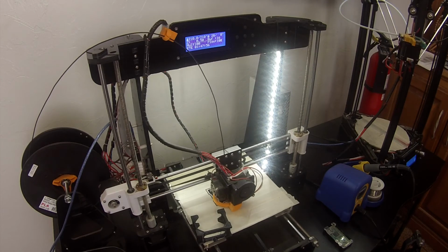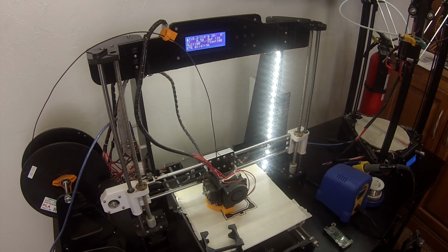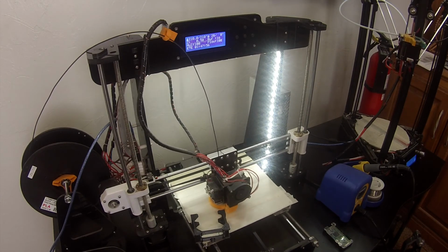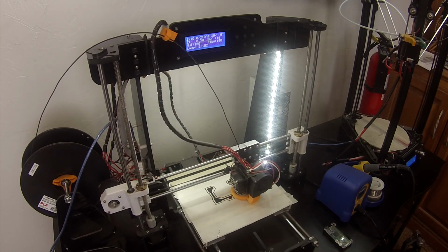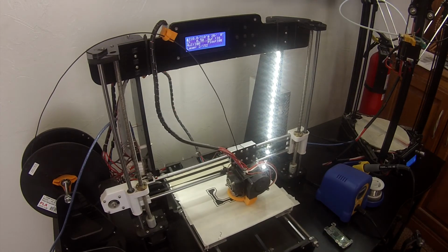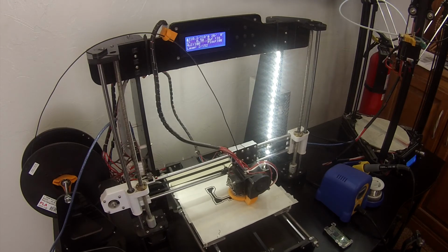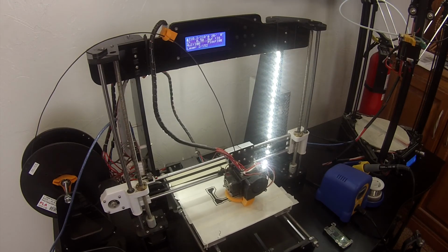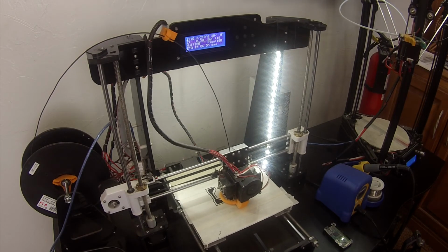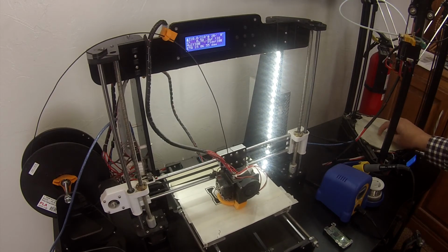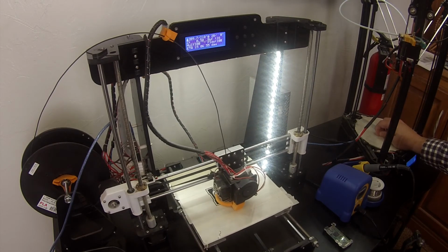So at this point, it's just a matter of watching the printer to make sure it doesn't catch on fire. That can happen. There's a decent amount of current being put into the heated bed, so a decent amount of current being put into the heated element of the printer. And whenever you're dealing with electrical heaters, especially resistive heaters like those, there is a risk if they get into a thermal runaway type circumstance that they could catch fire.